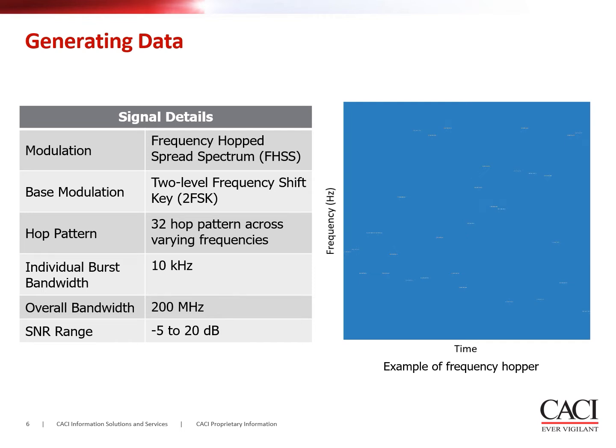This project used 3 different patterns of frequency hoppers, with one pattern being shown in the image as an example. Some of the experiments used the same relative pattern but with hops shifted in frequency, and others used different patterns altogether. Both data variations were used to test the ability of the Yolo algorithm to either detect an individual burst of energy or group of hop patterns depending on the experiment being conducted. Interferer data was also created and included noise, a narrowband binary phase shift keying or BPSK signal, and frequency hoppers with randomized patterns of varying durations.